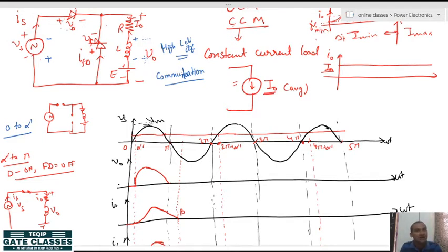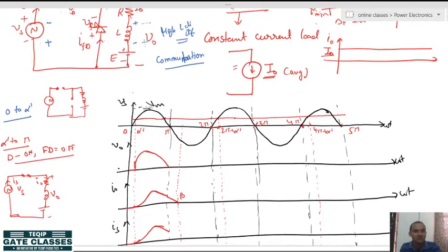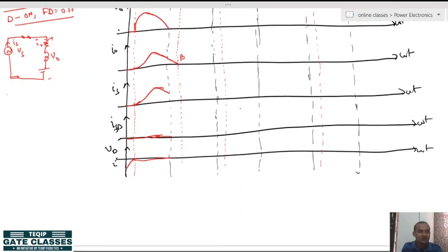Alright. So at the pi instant, this main diode will be off and this freewheeling diode will be on due to the high L di by dt of the inductor. So the load current will immediately commutate from the main diode to the freewheeling diode. Let us draw this instant, from pi to beta. From pi to beta, the main diode is off, but the freewheeling diode is on. So what will the circuit look like? The modified circuit will look like this.